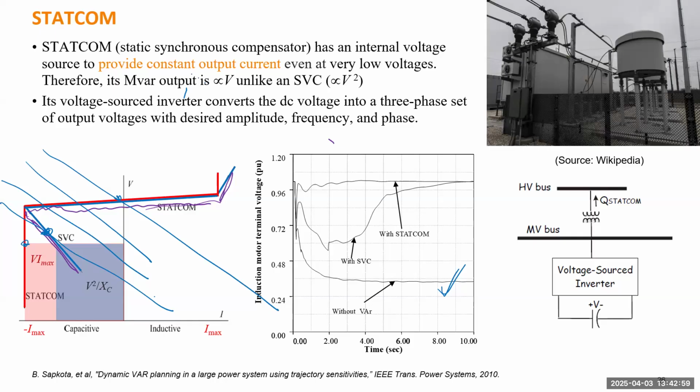So if you put the SVC there, it can mitigate the problem, but there is still some risk of staying too long at low voltage. So the STATCOM will be much better. All right. So this is my last slide for voltage control and regulation. Any questions? All right, no, so we will move to the next session.